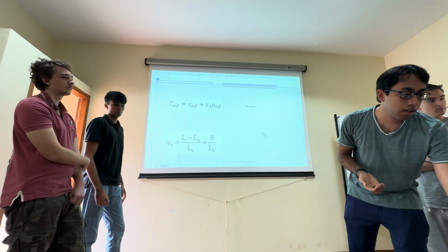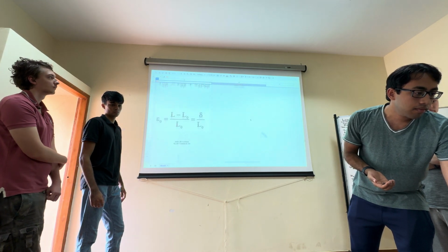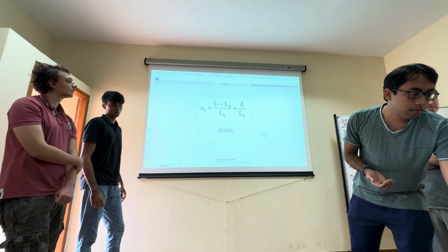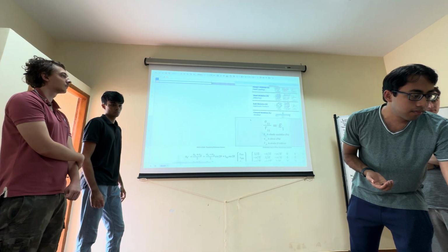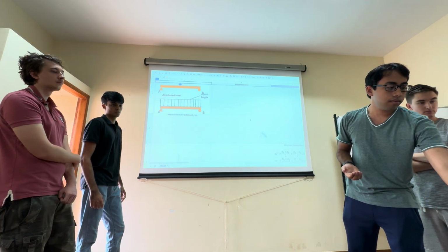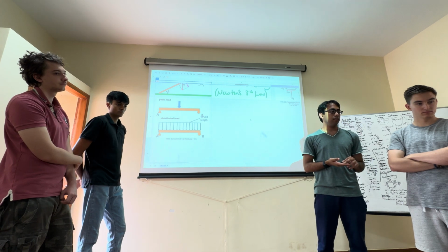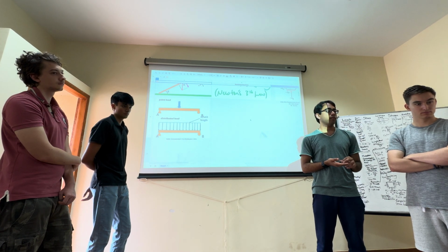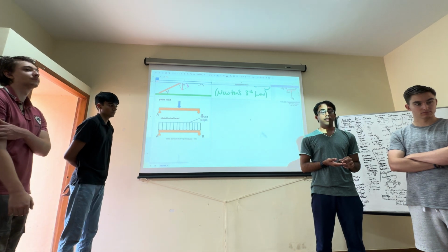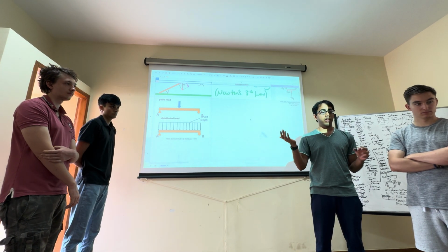Yeah, but the distinction between elastic and inelastic is more of a constitutive law, so it comes under an earlier column. But I see what you're saying in terms of the deformation. So it's good to classify that whenever you say just the adjective elastic or inelastic, it comes under the constitutive law, whereas when you're talking of elastic deformations and inelastic deformations, you might as well write out the word deformation explicitly. Later on we'll talk about specific examples of deformation with buckling and the bending moment.